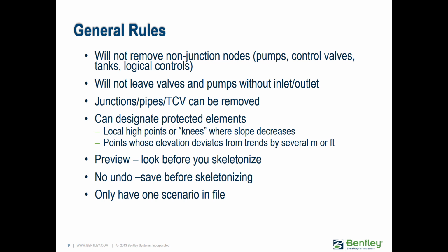There's also a preview option, so you don't just hit a button and then it's done and you can't go back. There's a preview option where you can see exactly what it's about to do before you click the compute button in Skelebrator. Although once you actually commit that change, if you compute and commit the changes that it's suggesting, there's no undo, so you can't go back to the way it was before unless you, of course, save a copy of the model before skeletonizing, which is certainly a recommendation.